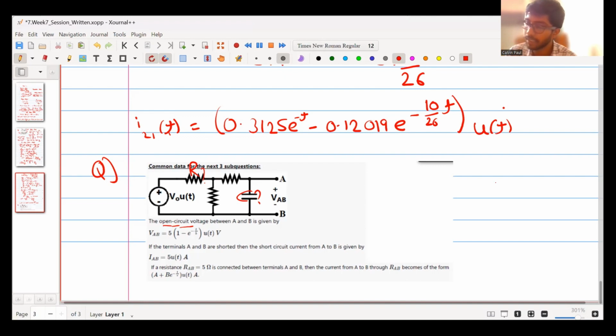So one theorem is there that is known as Thevenin's theorem. What does Thevenin's theorem state? Every circuit is modified into a Thevenin voltage source in series with an equivalent Thevenin impedance in series with the load resistance. So now in our question, what is the load resistance? Load resistance is given, sir, 5 ohms. So my load is given, that is RAB, that is 5 ohm.